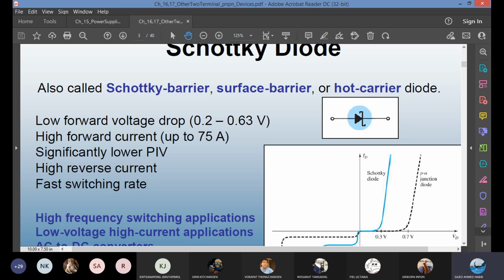Remember the diode turn-on and turn-off response time, the reverse recovery time for the basic diode. For this one, the response time is very quick, so it's a low number. The noise is lower. If you want an application in the ultra high frequency or very high frequency range, both the switching time and the noise reduction are important.